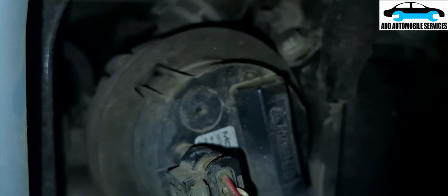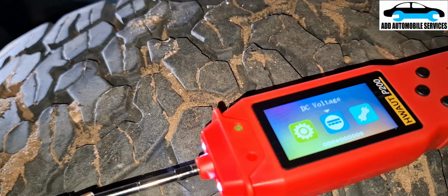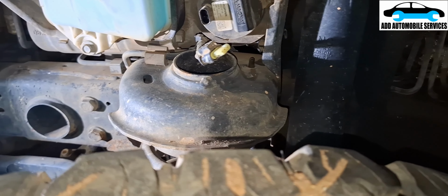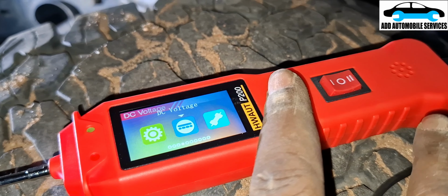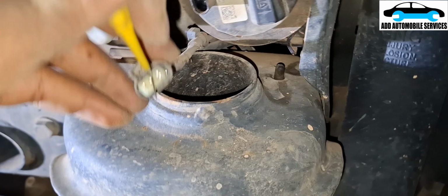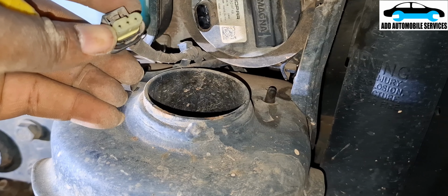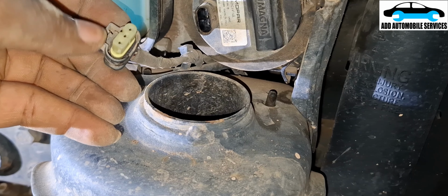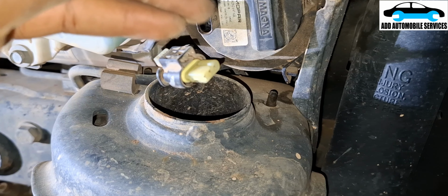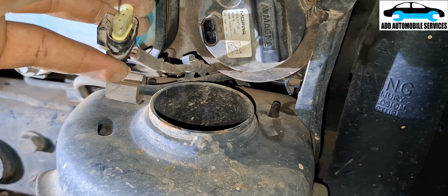So let me do the removal. So now that I've been able to remove the socket, I'm going to test the power, the ground, and the signal. So let me go to scope and let me test. From this point, this pin 1, which is red. This is pin 1, where the square is pin 1, pin 2, and pin 3. So let me check it quickly.